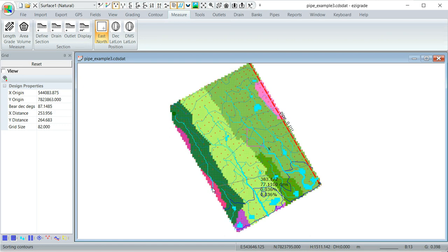So about there, that area is at that angle to that lateral gives us a grade of 0.04. If we came across, it's flat, but we really want the ground to slope up a little bit to, I believe, match the slope of the pipe. So yeah, to about there.